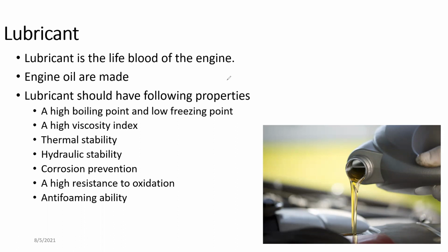Even though it is taken from crude oil, a lubricant should have some properties. The main properties are given here. Number one is a high boiling point and low freezing point. If the lubricant boils, it is going to vaporize, and if it freezes, it is going to turn into a solid.